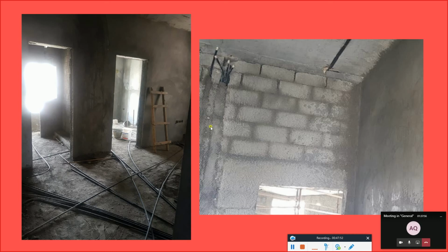Others are using meshes or steel as well on the edges. Normally, edges are easily affected. So in order to protect my edges, like let's say the edge of the wall, normally they'll be keeping some kind of steel. The steel will ensure that whatever hits that particular wall will not affect it. So these small items are going to protect you from small damages like cracks. For these cracks, later on you can go and solve them, but once again, it's better to avoid them from the beginning, since this particular mesh is not expensive.